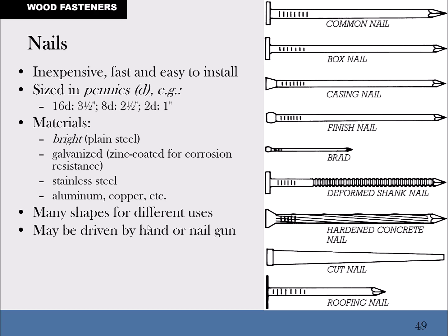But if you get the framing nailer where you're automating this by shooting nails in with a nail gun for framing, the 16D nail and the 12D nail and the 10D nail and maybe the 8D nail that you can shoot out of that gun, typically, they're all going to have the same diameter shaft. So the nail gun kind of changes that. But you could actually see that the 16D nail was much stronger because it was huskier, heavier.